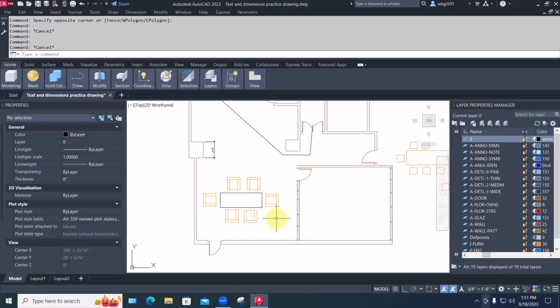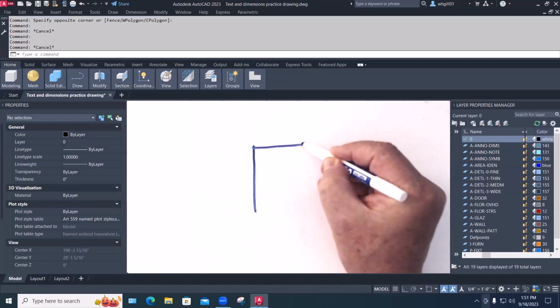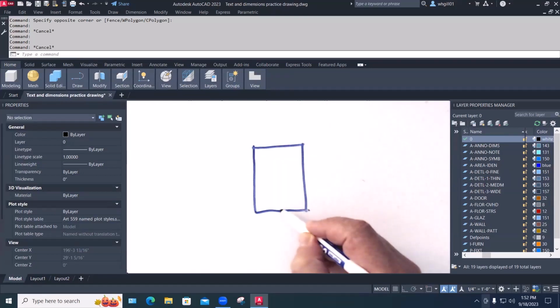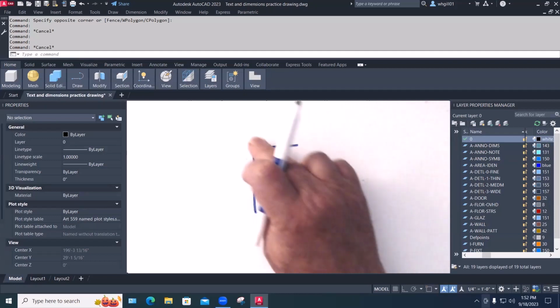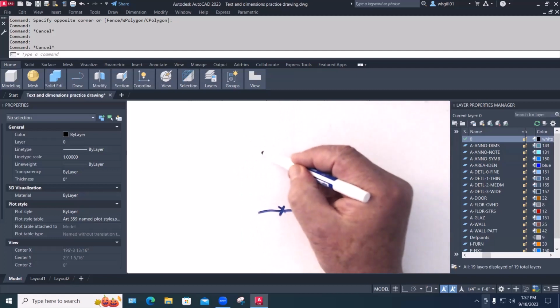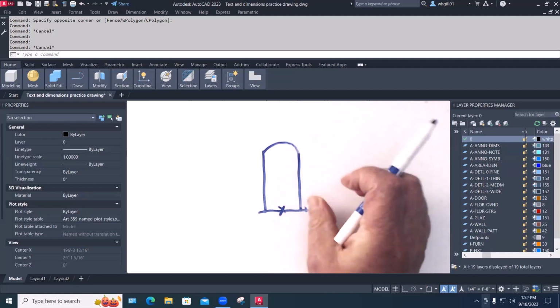Being able to redefine or refine a block as a project goes on can be hugely useful. I'll use an architectural example. A 10-story building, 6 windows this way and 10 windows that way. And you start out just by sketching in a rectangle for it and calling that block building window. So you start with something looking like this, just in your schematic design. And then he said, well, the one across the street is a little skinnier and has that arch, but we'll leave our base point here.